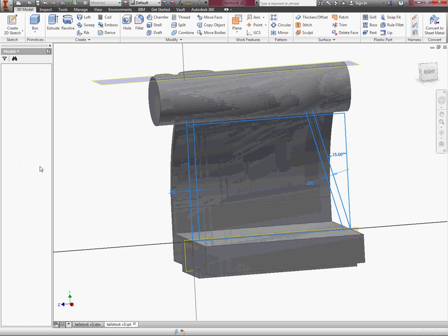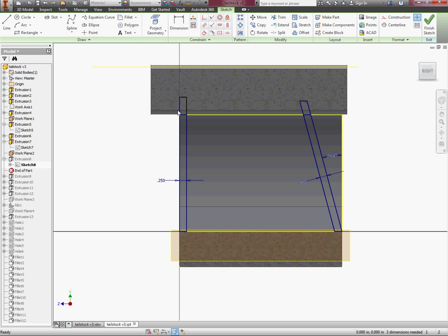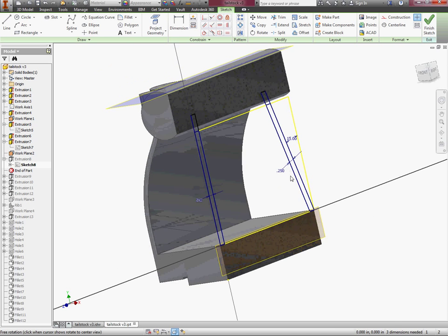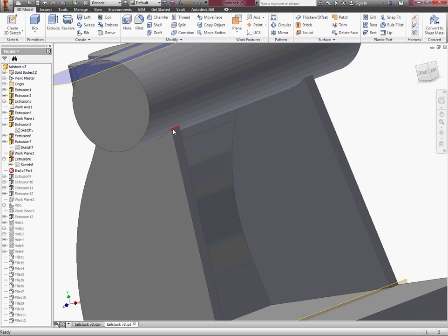Important thing here is these sketches, when you make them, if I hit F7 again, you need them to go up into the cylinder so that way they blend together properly. You can see I actually stopped even with the yellow line at first because even I forgot the first time, the yellow line represented where the bottom of the cylinder was. So it looked like my walls were missing a part. So I just add a little rectangle on top there, so that way when it goes in, it all blends together correctly. Otherwise you get a little gap here if you don't.